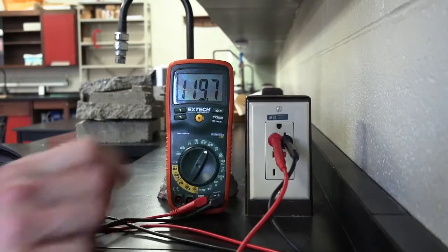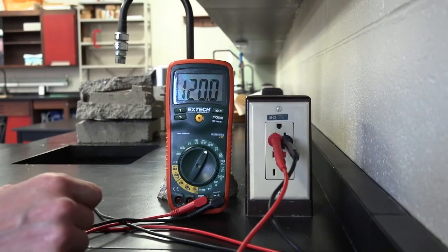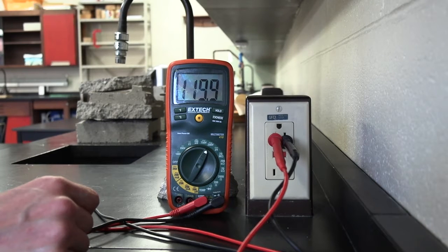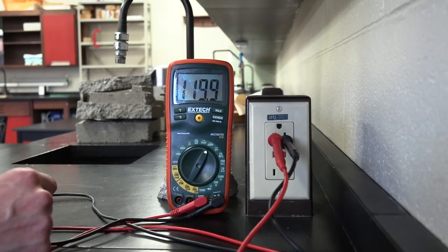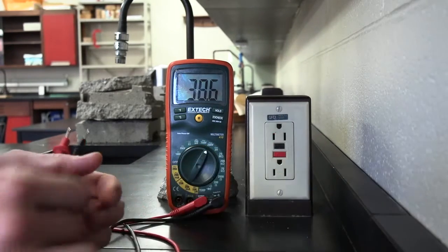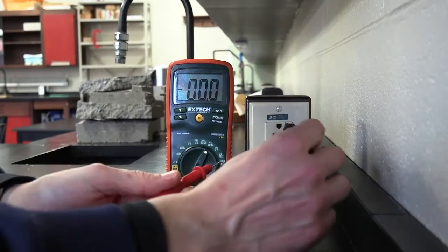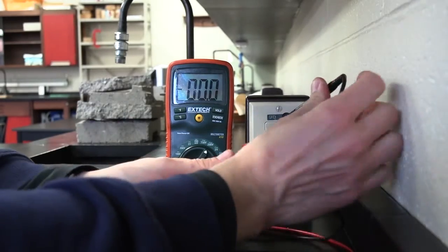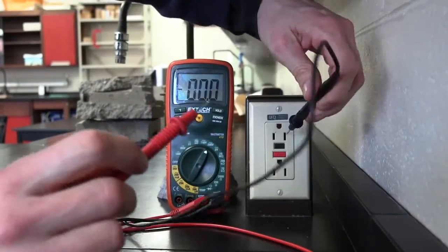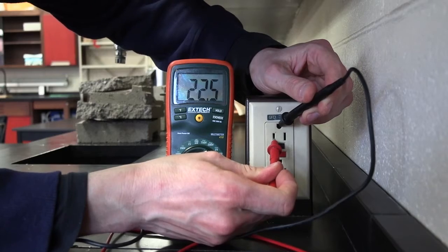So there I go. I've got them in there, as you can see, and it's somewhere around 120, which is the standard in the United States for the voltage of an outlet. In Europe, of course, you may have heard it's 220. They have a higher operating voltage. So I'll take these out now. So that's the voltage between those 2 prongs. But I could also measure the voltage between ground and that hot. Maybe I'll go like this from this side to maintain a good connection. And the hot, and I should get 120 also. Oops.